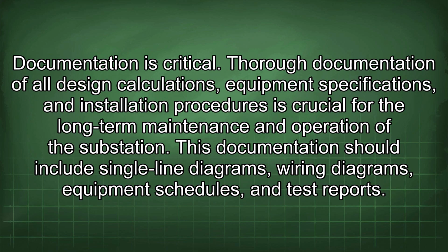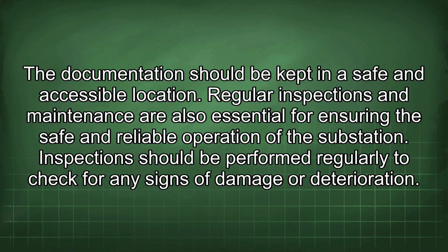Documentation is critical. Thorough documentation of all design calculations, equipment specifications, and installation procedures is crucial for the long-term maintenance and operation of the substation. This documentation should include single-line diagrams, wiring diagrams, equipment schedules, and test reports. The documentation should be kept in a safe and accessible location.